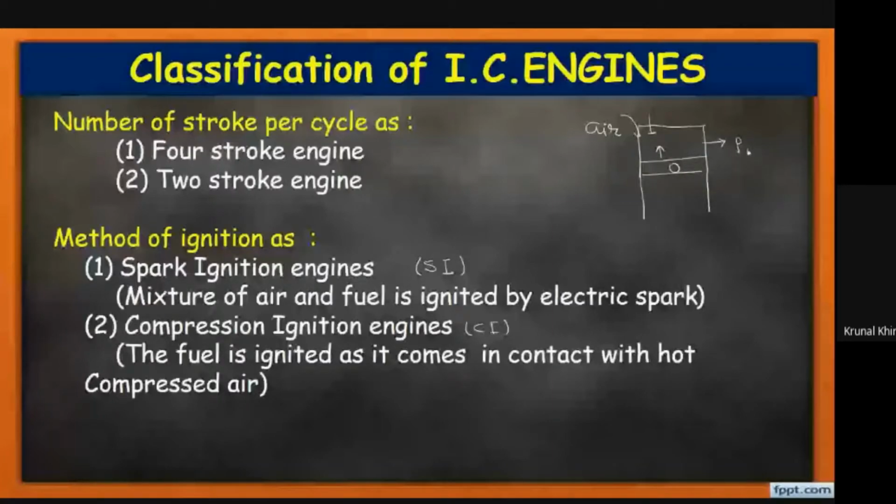At that time, from this injector the fuel is sprayed inside the combustion chamber, or the cylinder, and combustion takes place. That is not a single spark. It is a flame generated from many places, whereas in spark ignition there is a spark plug, and a single flame travels in the cylinder, or the combustion chamber.